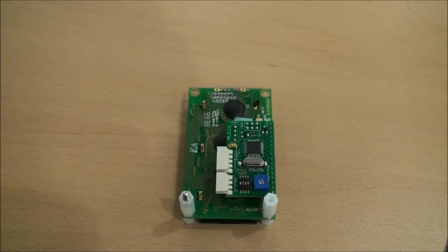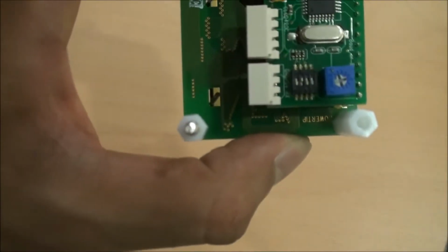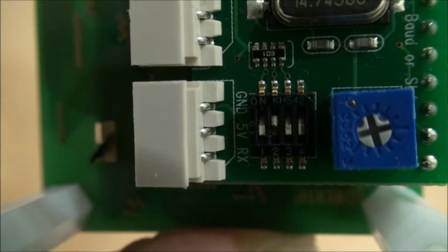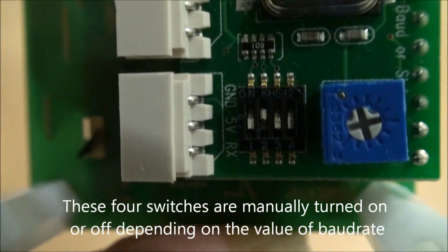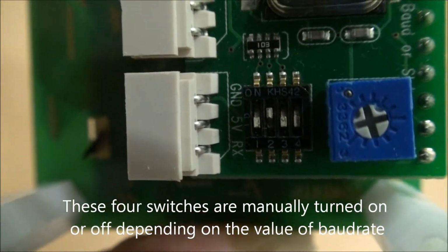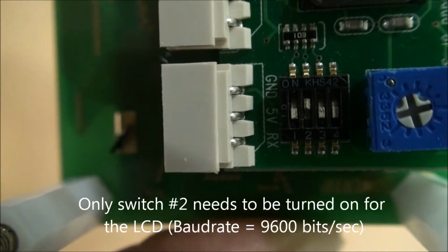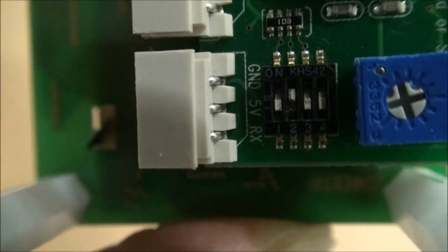There is one thing that you need to be careful about. If you look closely at the back of the LCD module, there are 4 switches. These switches are turned on and off depending on the value of the baud rate. In this tutorial, we use the LCD whose baud rate is 9600 per second, so only number 2 needs to be turned on.